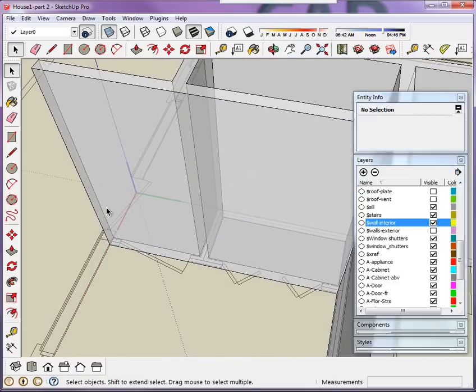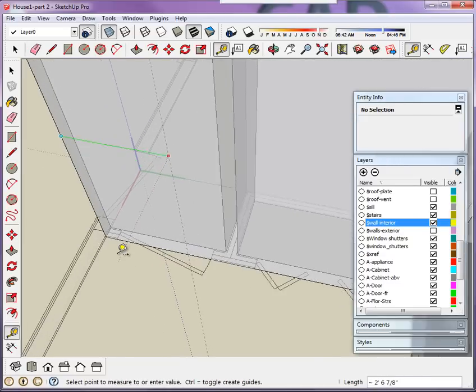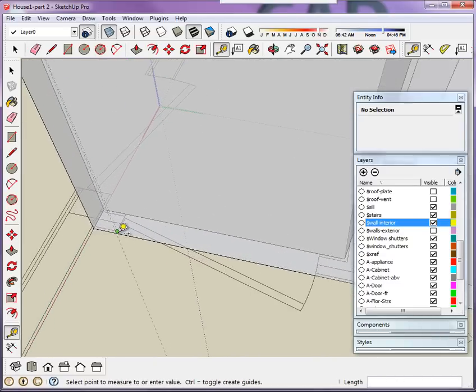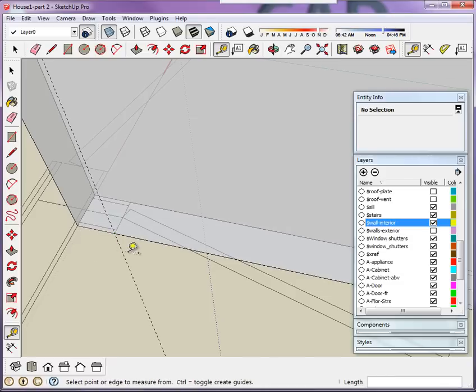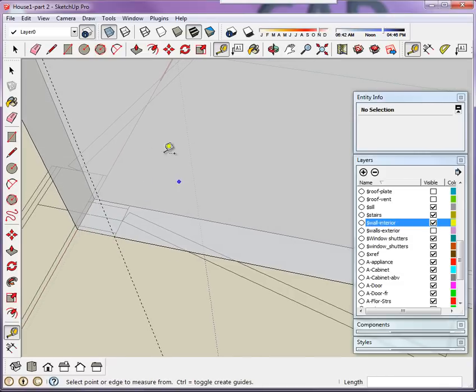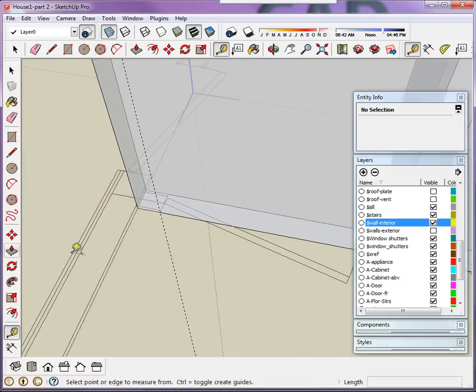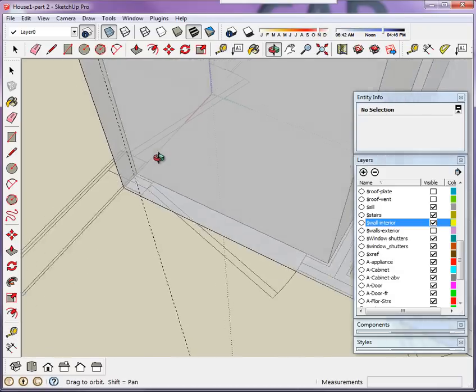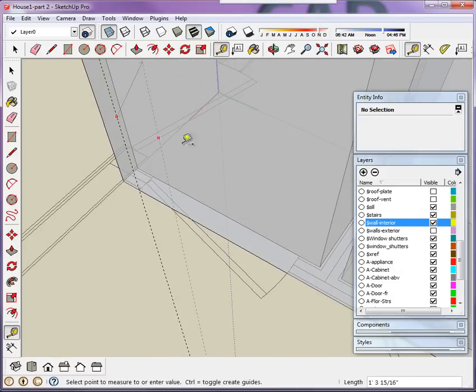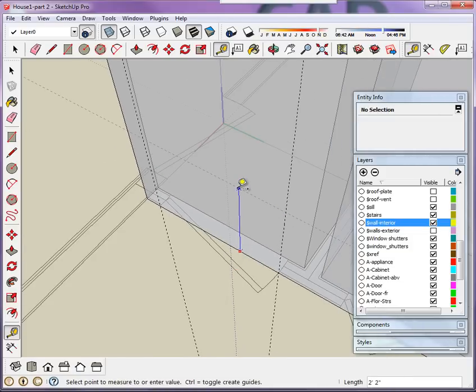We could do all the same doors at once if you like, makes it easier. Let's use tape measure T, drag our guidelines here, and then zoom in and make sure you're on the outside face, right? You're going to be punching the holes only on one face, so make sure you stay consistent and do the guides on the exact same face. Pulling along the green axis here for the right side opening, and then from the floor or from the bottom of the walls there to 6 feet 8 inches.